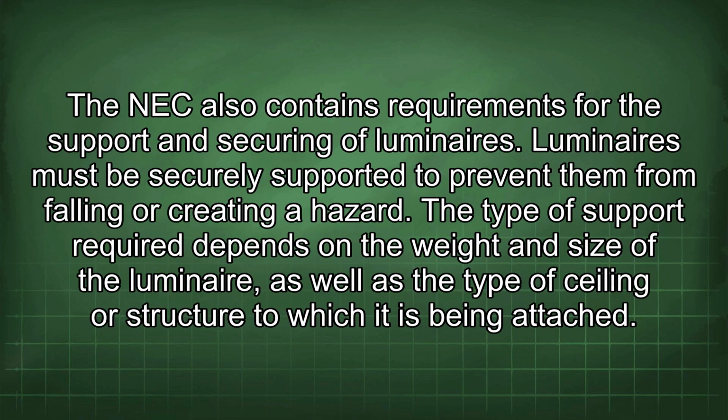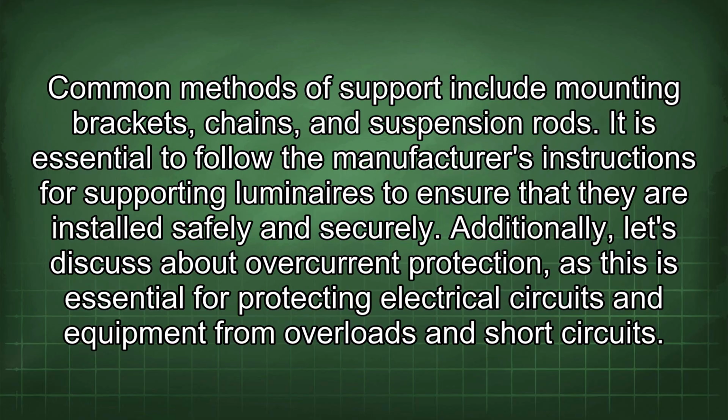The NEC also contains requirements for the support and securing of luminaires. Luminaires must be securely supported to prevent them from falling or creating a hazard. The type of support required depends on the weight and size of the luminaire, as well as the type of ceiling or structure to which it is being attached. Common methods of support include mounting brackets, chains, and suspension rods. It is essential to follow the manufacturer's instructions for supporting luminaires to ensure that they are installed safely and securely.